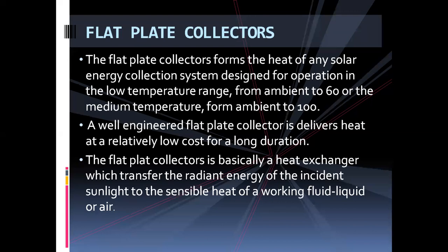So here it is told that the flat plate collector is basically a heat exchanger which transfers the radiant energy of the incident sunlight, that sunlight that is incident on the collector. It will transfer that radiant energy to the sensible heat of a working fluid, liquid, or air. It will exchange the heat and make it usable for the users.